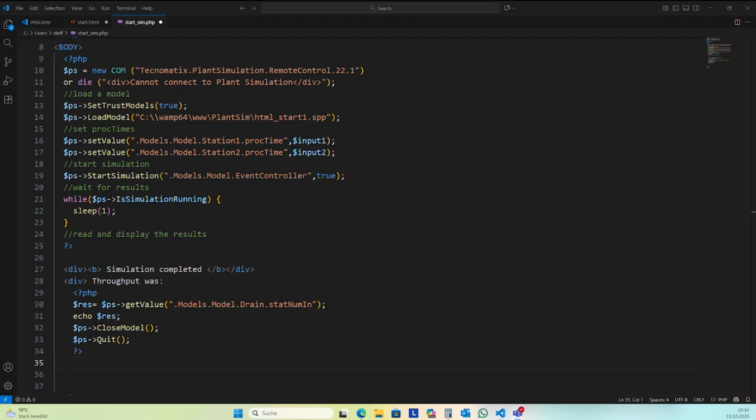And when we do that, the Python implementation runs this makepy file. It creates a generated cache file that says, here's the implementation of this COM object, let's hold this in memory. It's a little buggy, and it also requires us to go in pretty often and flush that cache and rebuild it, even if nothing about the version of Plant Simulation has changed.